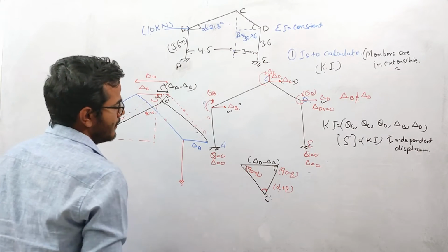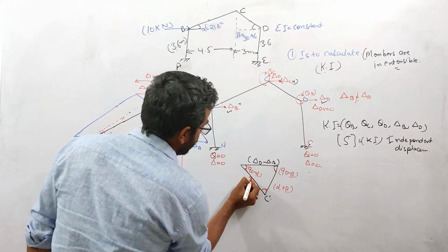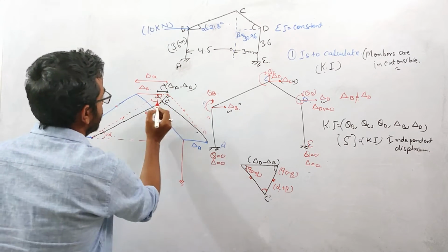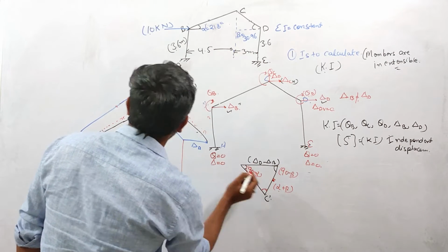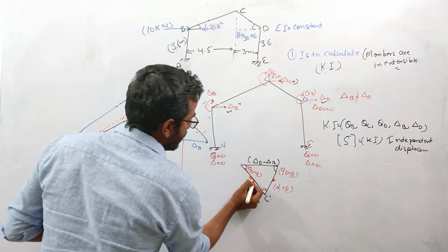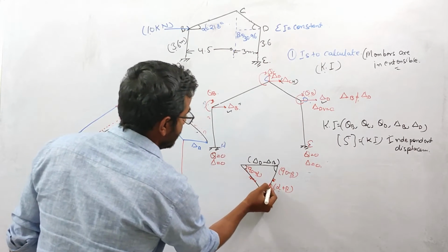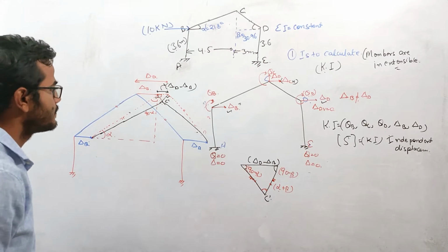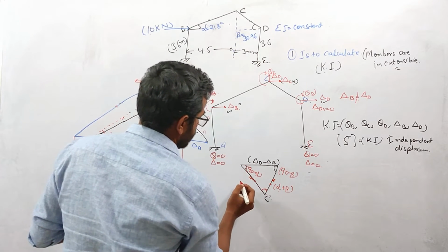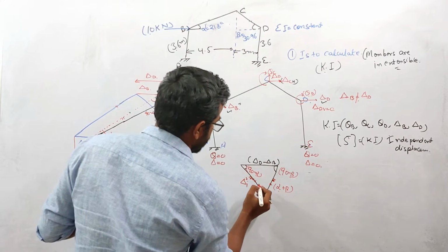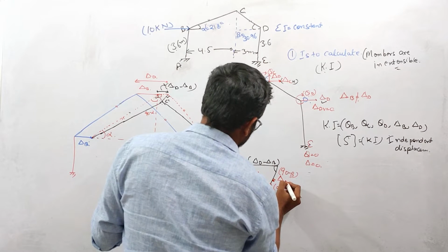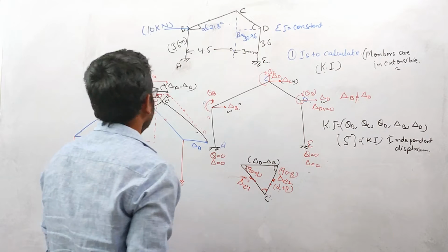So guys, now you can see that we basically require these two displacements. This figure is an enlarged view of this point. These two displacements will be responsible for generating moments in this portion. For this member, the sway will be due to this displacement. The moment generated due to sway will be due to these two displacements, right? So now let us suppose this is delta C dash 1, and this is delta C dash 2, right?